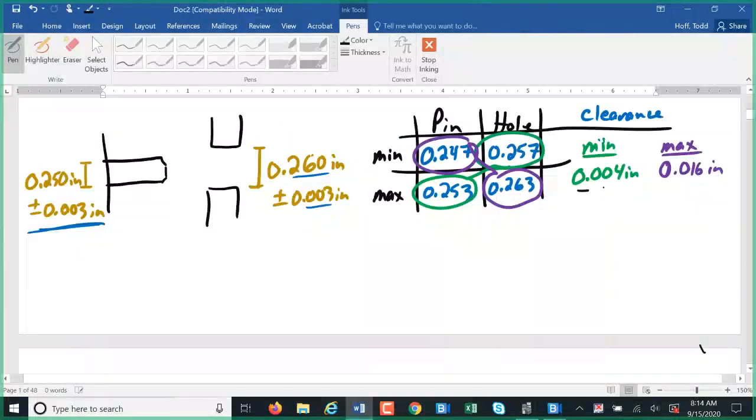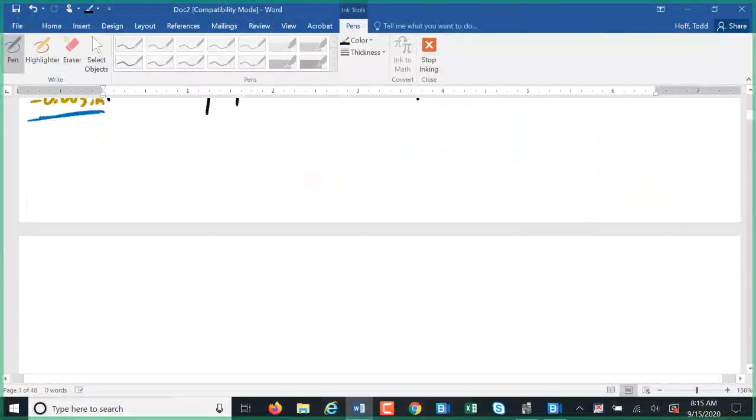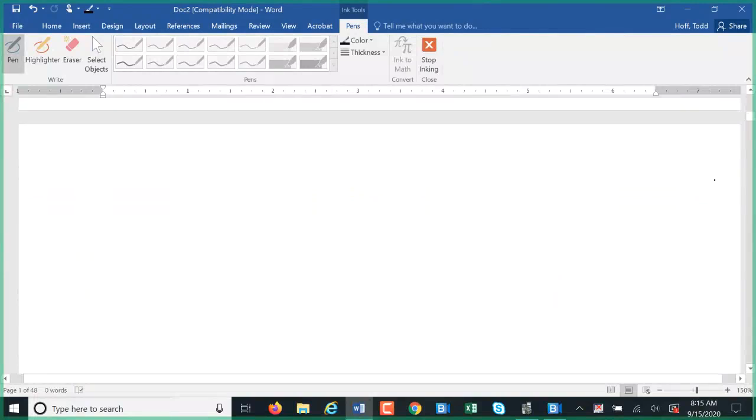And that is a pretty healthy sized range between the minimum and maximum clearance. So even though, like we said, the allowance may seem small enough on a single part, when those parts start interacting together, the combined allowance, or it's called tolerance buildup or error buildup, can create some very large differences.